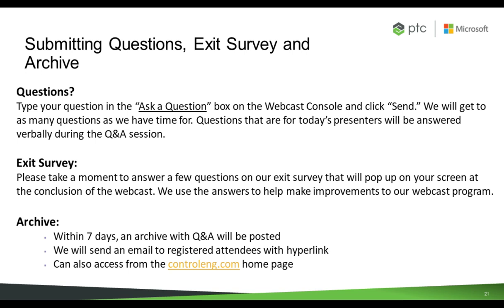Ray, we're back to you. As we asked previously, with option 3 in the presentation, can IoT Edge handle both OPC UA and MQTT connectivity simultaneously? Yeah, it certainly can. And sorry about the double mute on that with my setup. The UA capabilities we're talking about are leveraged through a module running within the IoT Edge runtime. To get technical, that's one of the container modules running and active within that runtime environment, connecting to an OPC UA server.